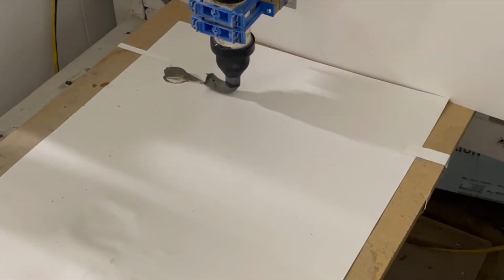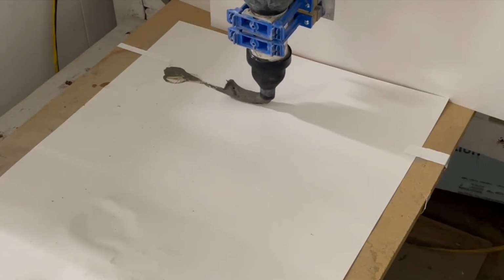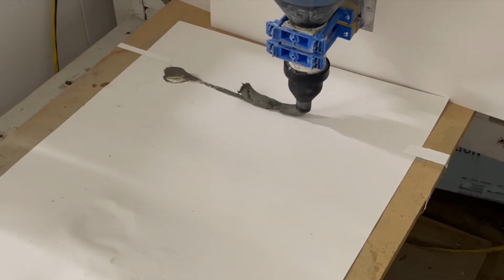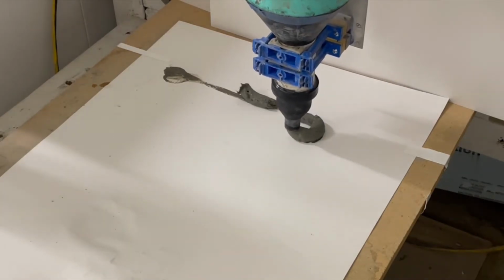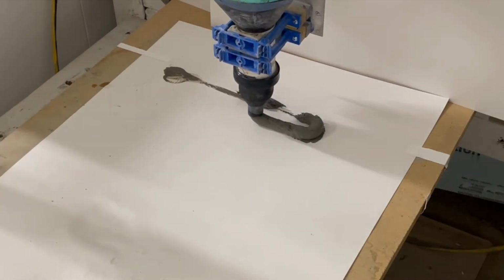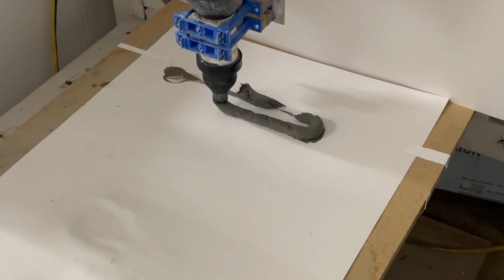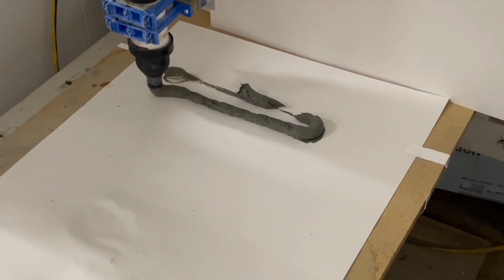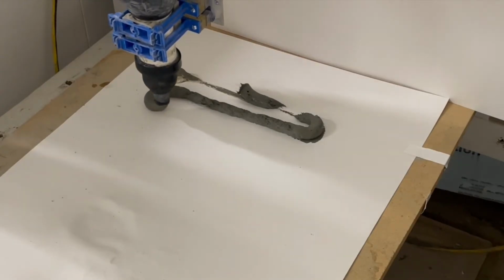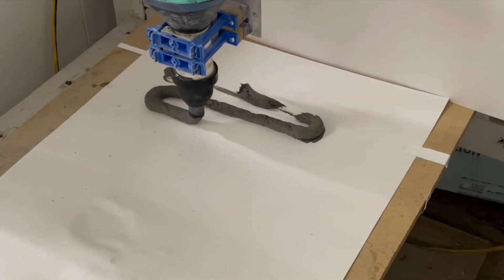Another lesson that we learned is the importance of syncing the extrusion rate and the printing speed with the material parameters. To achieve extrudability, the velocity of the print head should be synchronized with the extrusion rate. Otherwise, the extruded layer is likely to become either crumpled or torn or discontinuous.